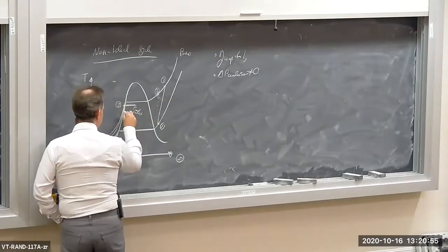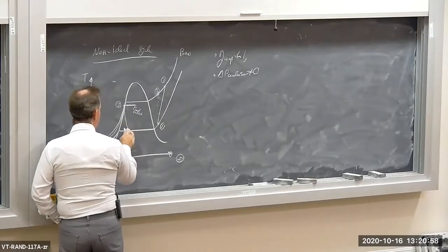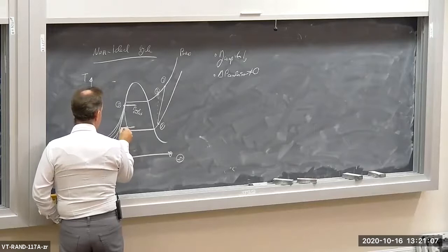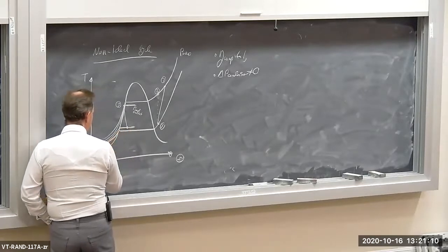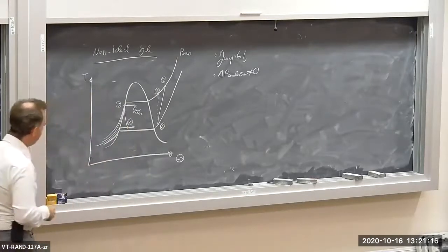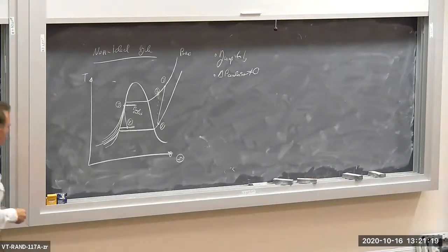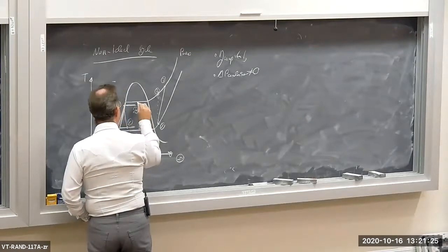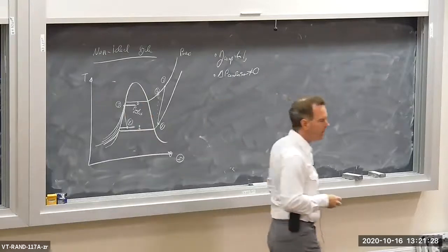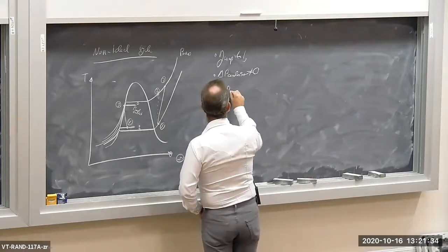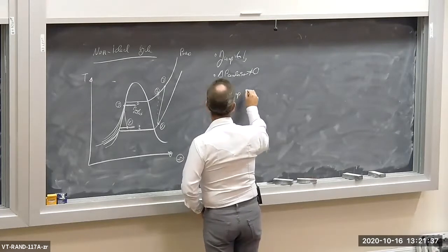Then, of course, we have the expansion in the throttle. Now, maybe we also have a pressure drop across the evaporator. So here's my evaporator inlet state at state 4. And then we could have a pressure drop, just like in the condenser. We could have a pressure drop in the evaporator as well. So delta P evap could also not be 0.